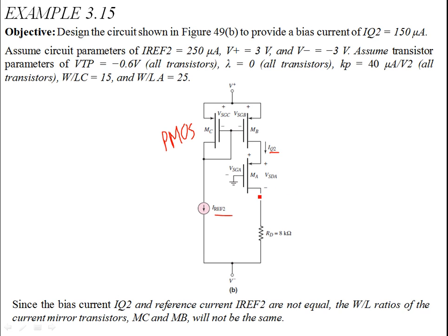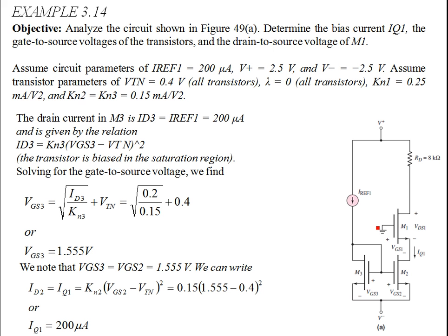Even if these transistors are in saturation, if you recall previously, here we have this M3 and M2, which are NMOS, and they're used to provide a constant current bias to the transistor M1. So in order to stabilize the Q point, that's the story. So this IREF, which is the drain current ID3, we set to be equal to ID1.